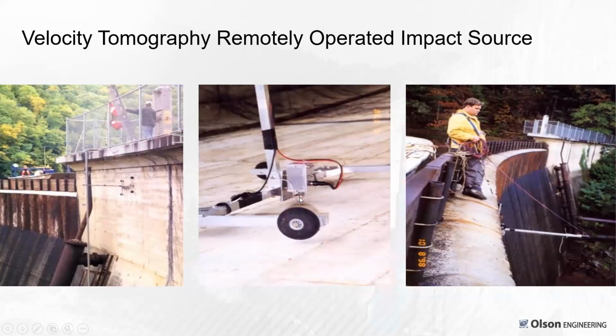You could perhaps see a little better here, these impulse force transducer and the solenoid that drove it. So when we would push the button, we'd hit it typically 4 times at a given elevation and record the response of the hydrophones that were underwater on the upstream dam face. Here you can see it on the dam.